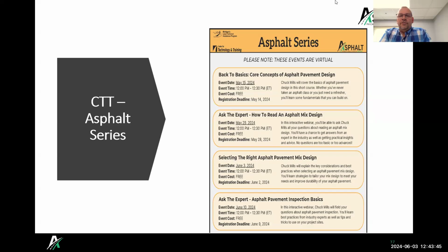Yeah, I think the cold weather really comes down to when we're selecting the polymer modified or the performance graded binder. That second number, the -28, is a typical binder that we'd use basically for the lower peninsula here in Michigan. Up in the UP, we use a -34. That number equates to what we call cold temperature protection.